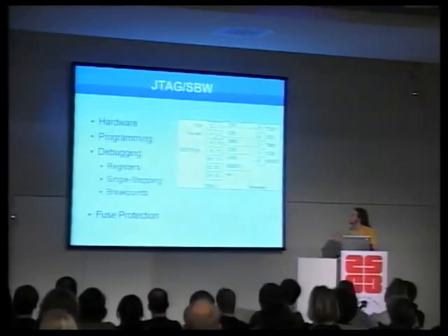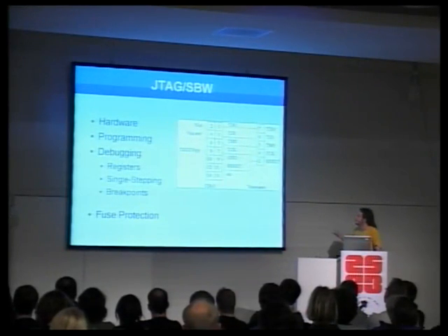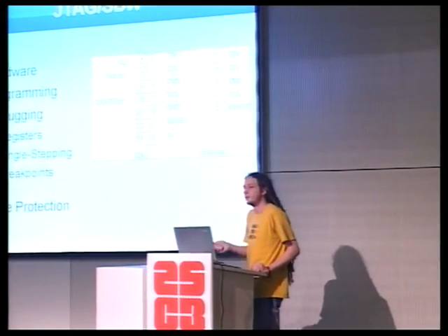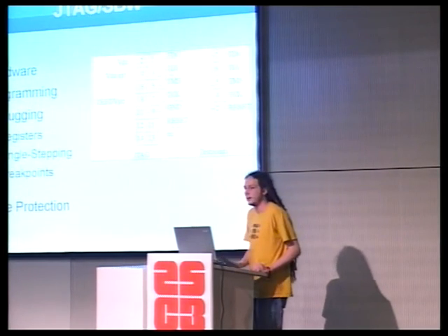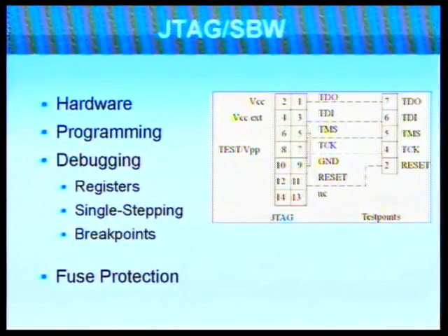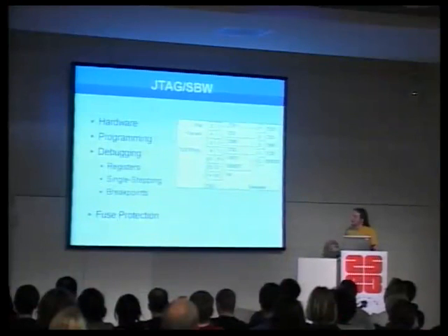Usually when you program this board, you use JTAG or SPI-by-wire. And in the case of JTAG, you connect to the board, and there's a physical fuse that can lock you out. If you're not locked out, you have complete control of memory. You can debug the device. You can single-step it. You can read from memory, write from memory. And there's no concept of a password.